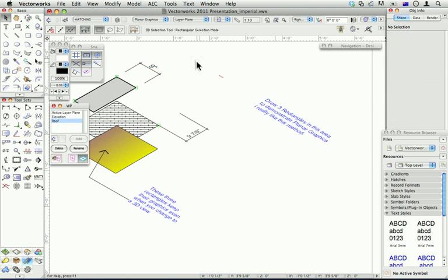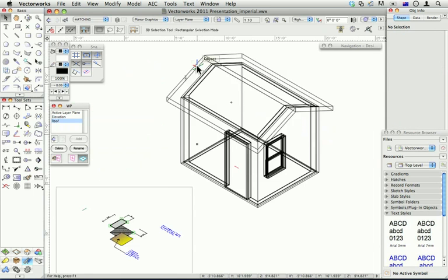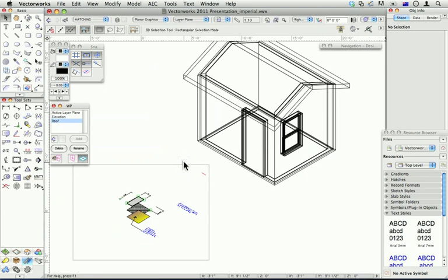Now I've actually got a part of a building here as well. So if I look at everything on my screen, you should be able to see there's also a building there. I'm going to choose one of these objects, and I can also set layer planes like elevation or roof. Now I talked to you before that 2D isn't so much 2D but planar. So we can choose a plane like an elevation, and I've now got a working plane on that elevation.